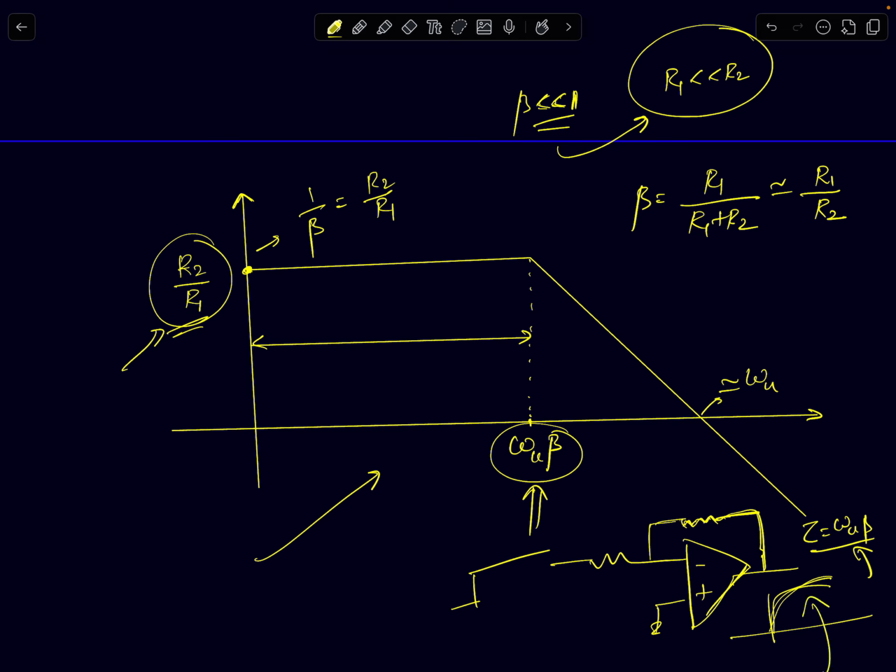So that's it about Opamp amplifier circuits, and how their frequency response characteristics change if I include Opamp's finite UGB. Ideally these are just amplifiers, so you would expect them to give you the desired gains for all frequencies. But if you consider Opamp's finite UGB, the characteristics change. These circuits will have a different frequency response, and we studied how the frequency response graph looks for the 3 popular architectures: voltage buffer, non-inverting amplifier, and inverting amplifier.